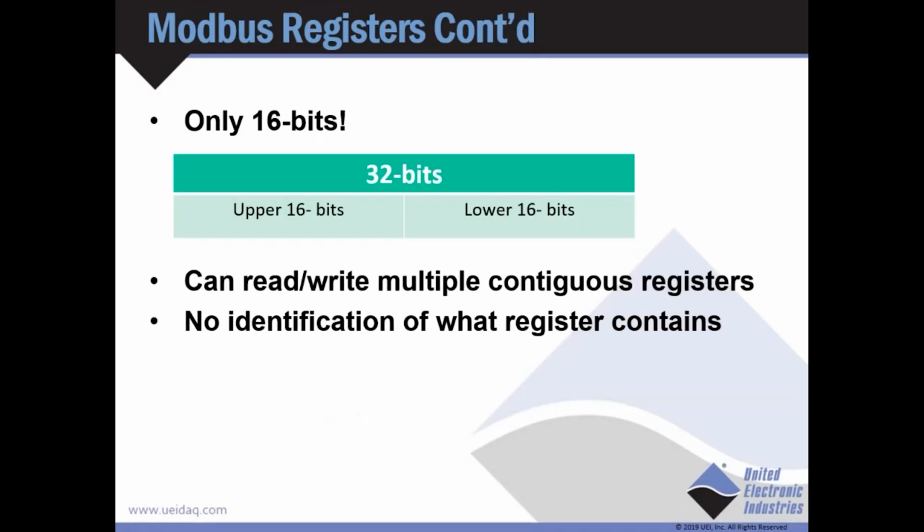From the previous slide, you may be thinking, 16 bits. What can I do with 16 bits nowadays? Well, we can just put together two contiguous registers, and then we get a 32-bit value. We can do that to represent our 32-bit floating point precision values. Well, what if I need 64-bit? Just as easy. We can now combine 4 registers of 16 bits to create a 64-bit value.